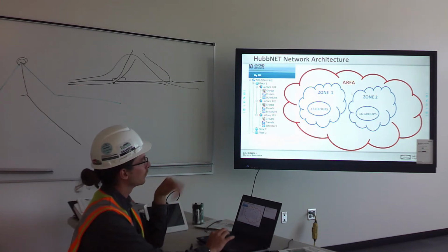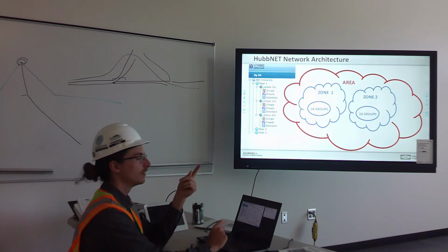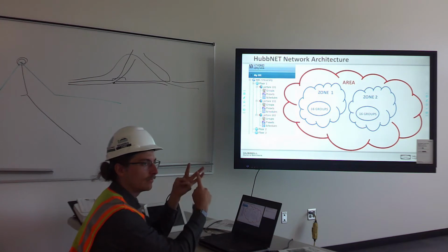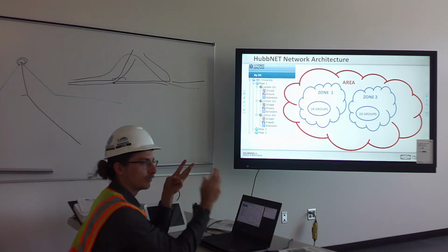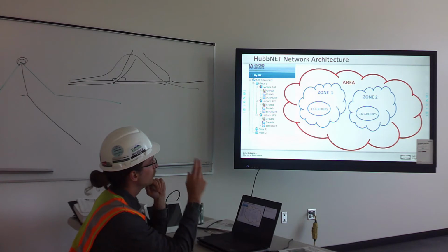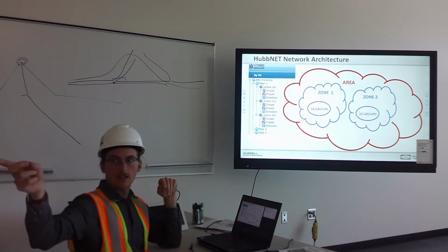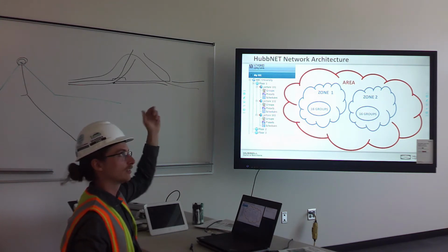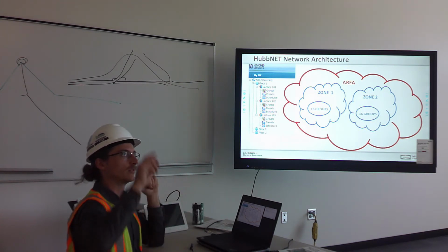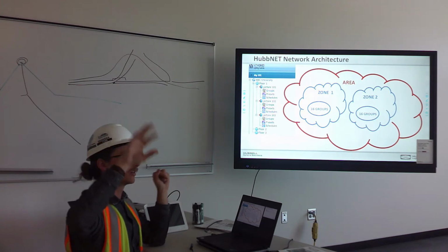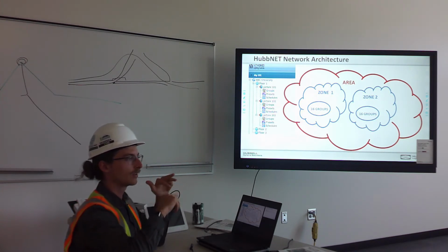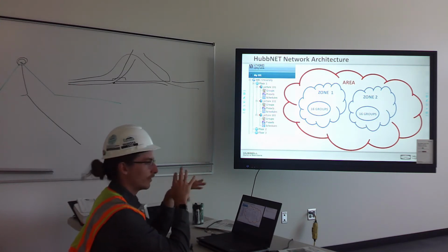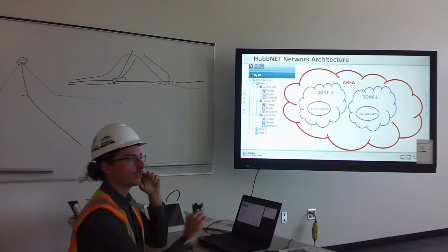So just an interesting point, if you have a switch that's in group 1, zone 29, area 10, it's going to have that information programmed into the switch. So say you take this switch out of the classroom and plug it in all the way on the other side of the building, it's still going to control this room because all the relays and controllers are set to that same area, zone, and group. It's just a good concept to understand of how everything's talking to each other and working together.